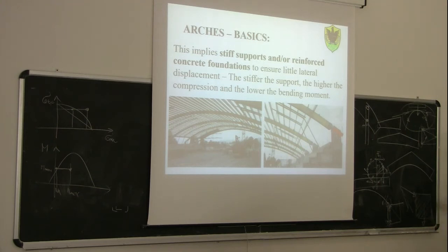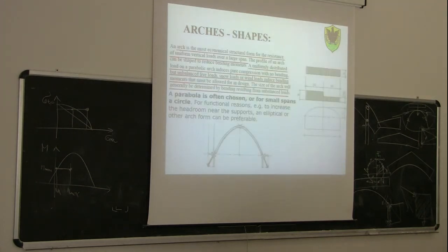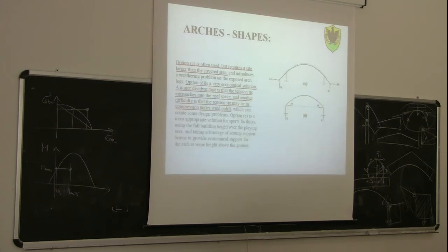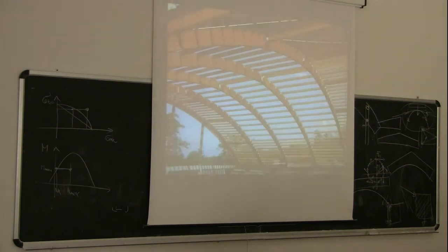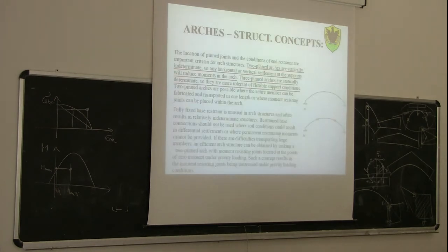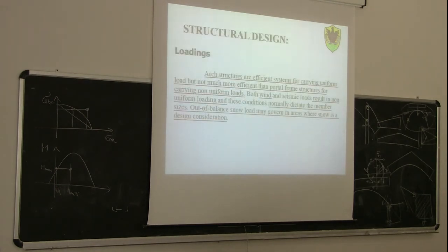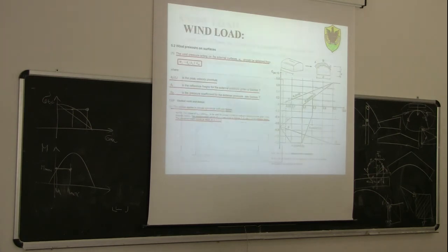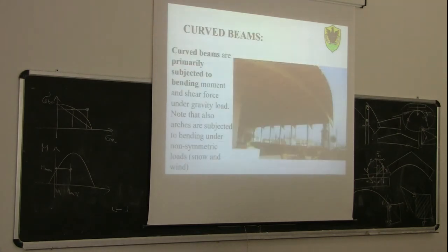The bending moment is going to increase, and the axial force is going to decrease. So the problem why I think this system here does not behave as an arch but as a curved beam is that this support is very flexible in the horizontal direction, because as you can see it's made of steel, a very slender steel column, which will be subjected to some horizontal forces.